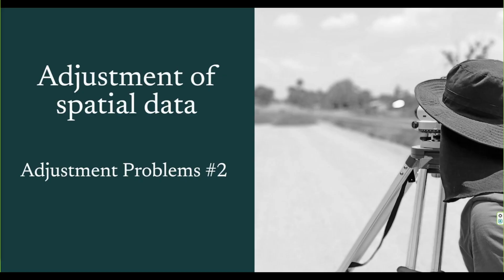So to recap episode 1, in surveying and metrology and related fields, we work with spatial measurement, so what we call observation in general. These can be distances, angles, directions, coordinates, height differences, any measurement of geometric quantities. Adjustment is the mathematical process we use when we have redundant measurements. More observations than the minimum required to determine our unknowns.